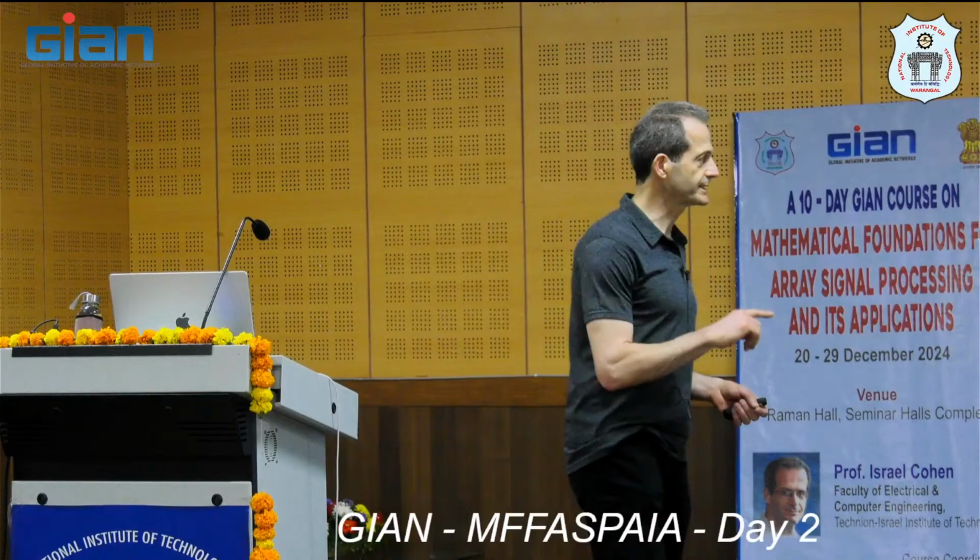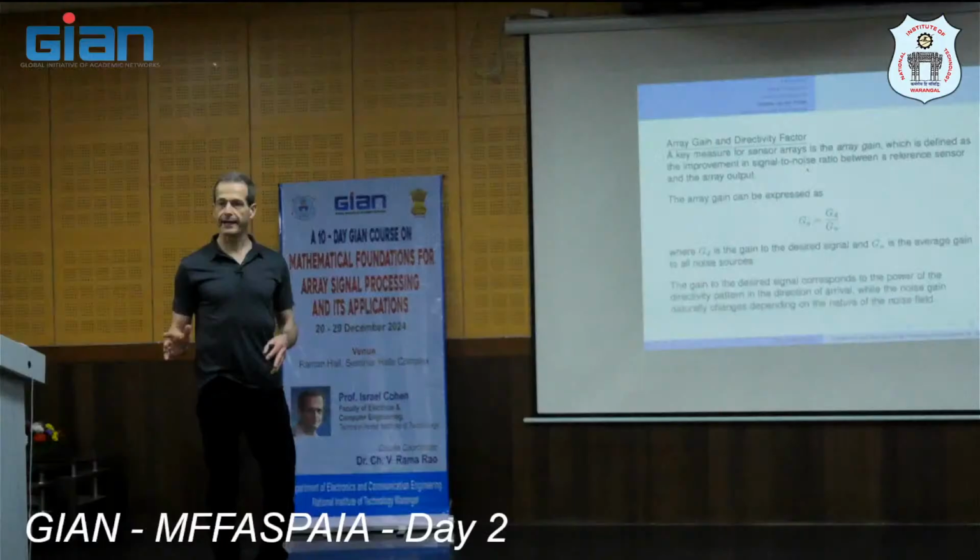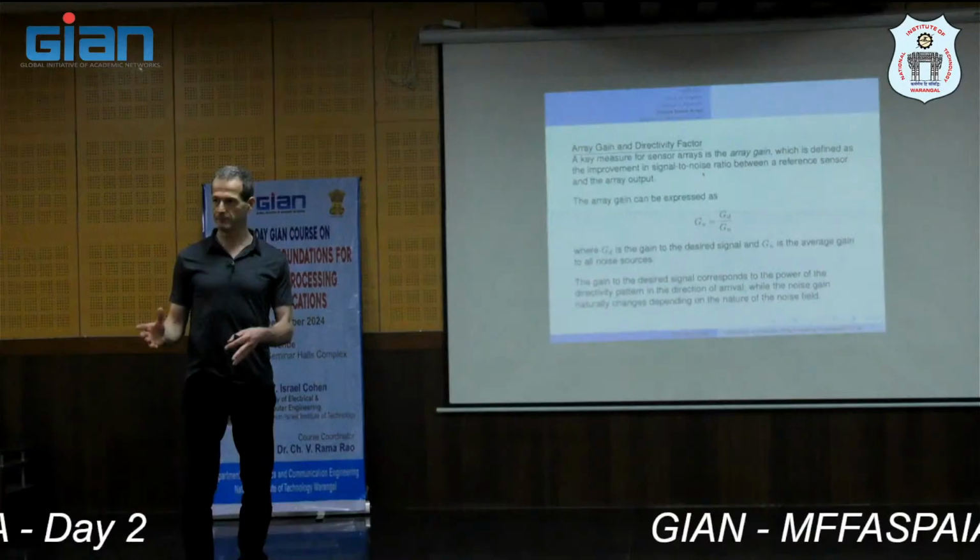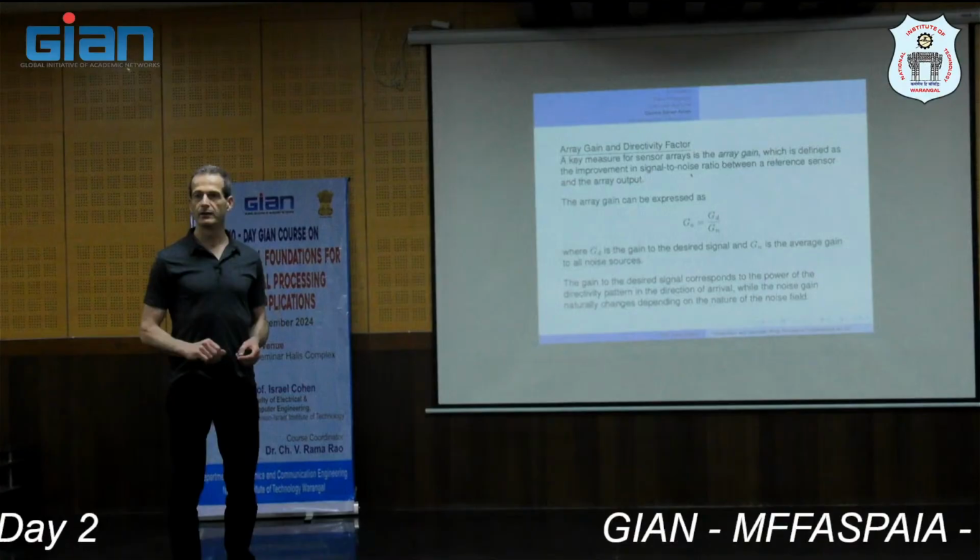Okay, so yesterday, first, do you have questions? Even if you have questions about what we talked about yesterday, you can just interrupt and ask. We will continue from the same place. Yesterday, we talked about array gain and directivity factor. Array gain is the improvement in signal-to-noise ratio of using the array beamformer compared to a single sensor.